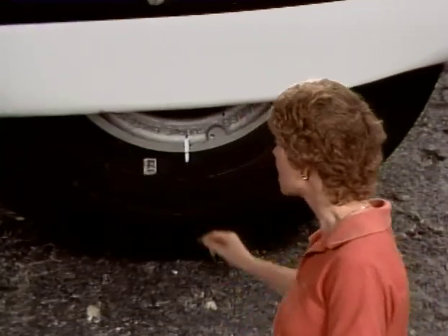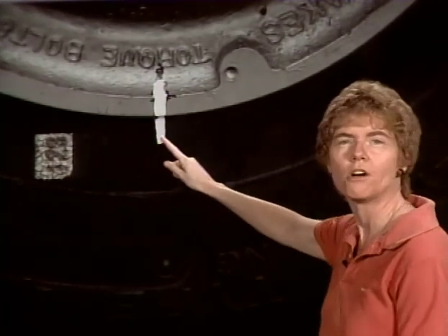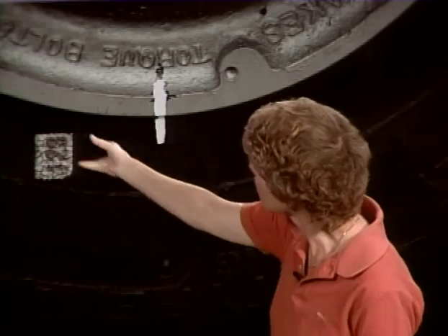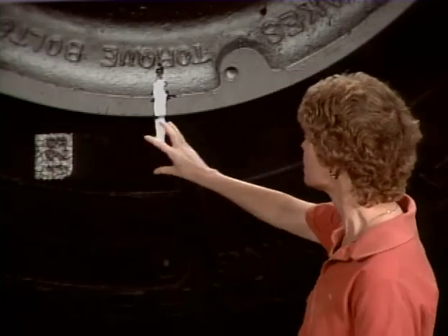Now, in a lot of cases, a tire will have a stripe or a mark like this that goes from the rim of the wheel down onto the tire. A stripe or mark like that is a slippage mark. The purpose of that is to be able to look at the wheel assembly and say, okay, has this tire slipped around the rim of the wheel any? If it has, it's an indication of a problem, possibly of some very bad landings, some problem that has actually slipped the tire around the wheel, which is definitely not something that you want to have happening.